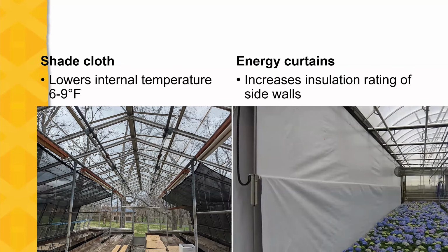Another thing that I want you to take note of is that, and I've seen many people do this because they're short on storage, there's nothing obstructing the fans. They're not storing things here. They're not parking trucks here. You want to have free airflow here. You don't want to obstruct here. Another example here, there's fabric here. I don't know if you can see it in this picture, but there's a fabric here